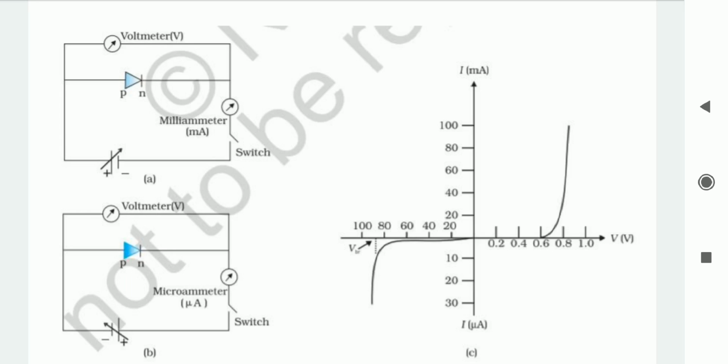So a PN junction diode allows the flow of current only in one direction, only in forward bias condition, where it offers very low resistance compared to reverse bias condition. This property of the diode we can use in many applications. Mainly it is utilized in rectifiers, to rectify AC voltages.